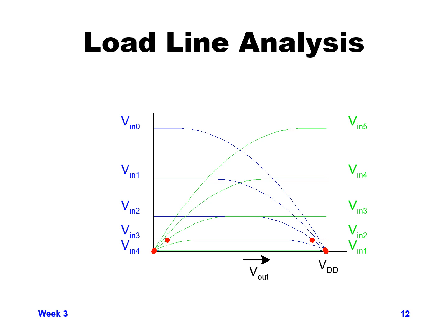So when we look at the full set of curves here, we'll see that for changing our Vin between 0 volts and 5 volts, we get an output voltage that, at least for the points that we plotted here, is going to be pretty close to either 0 or pretty close to VCC for all of the choices we have here.